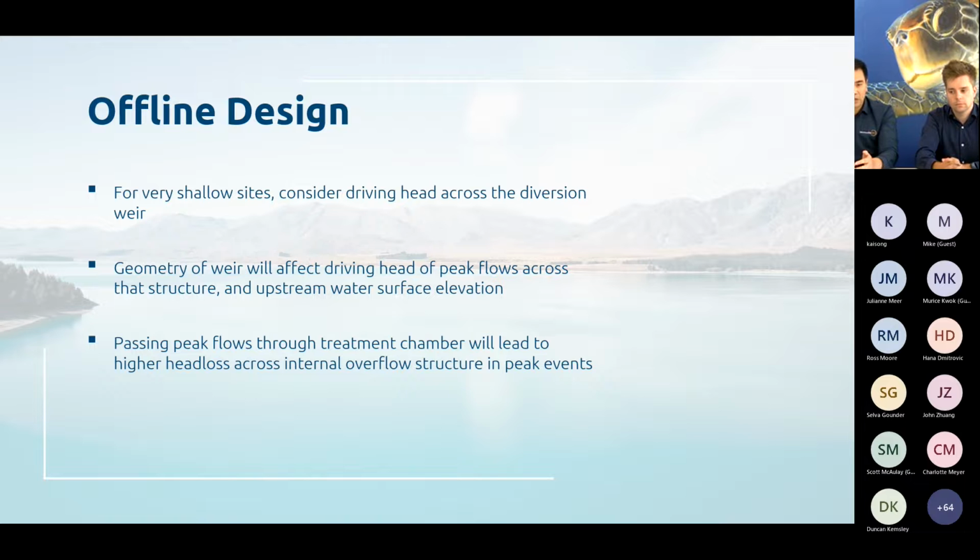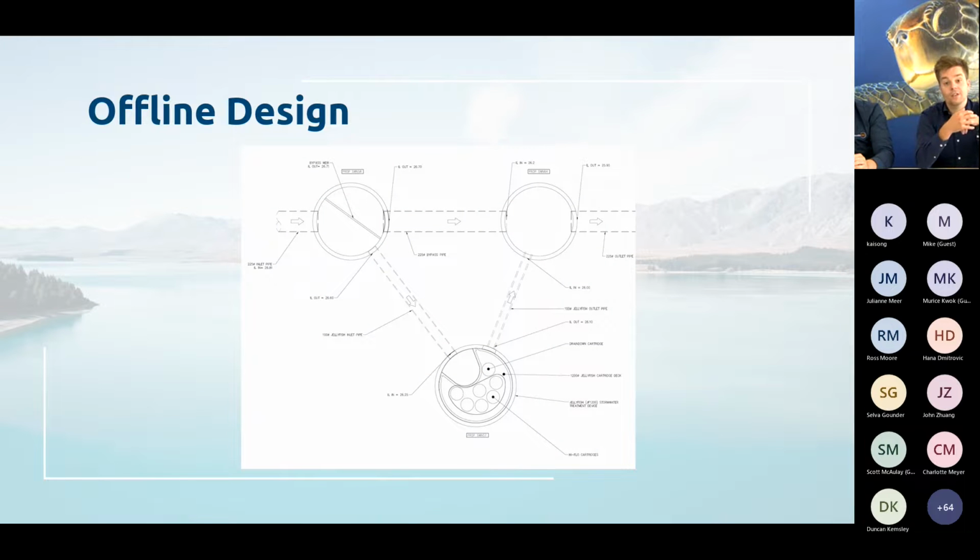And it is definitely one of the important design components around the treatment system to ensure we prevent any flooding on the upstream network. So applying that then to how do we, say for Auckland Council, how do we design a treatment device to be offline? And the answer, or one of the first answers, is to have an upstream structure that has the diversion and the weir included. So here you can see water from the site flows to the collecting manhole.